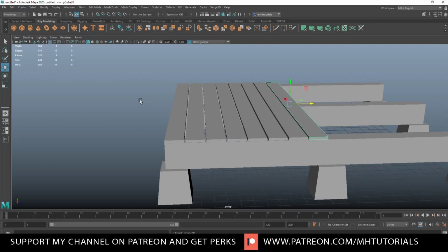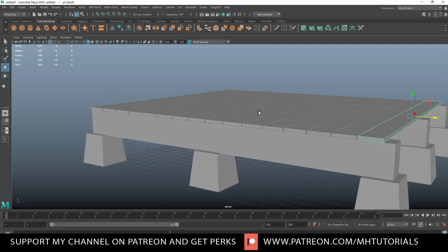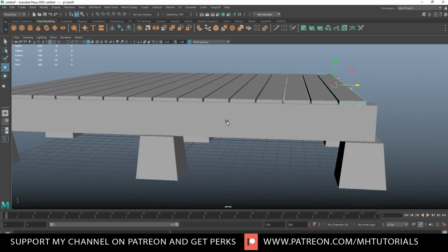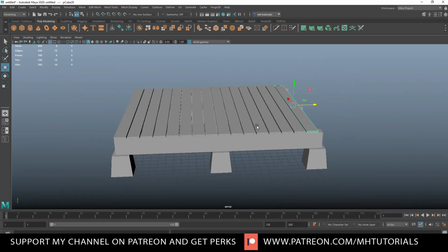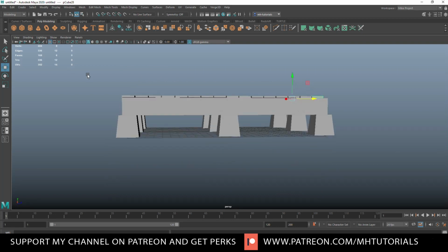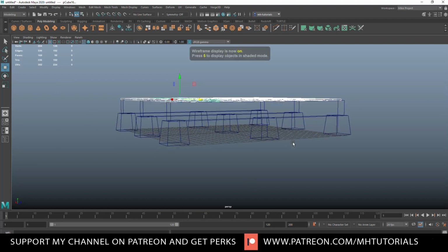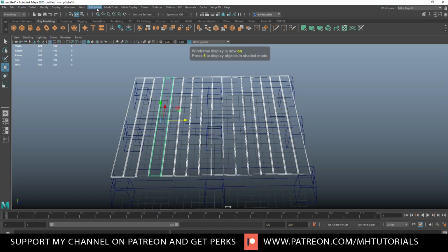And then we're going to hit Shift D and move that over, right? Now, as you can see, we're missing just a little bit of space there. There's an easy fix for that. We're just going to drag select it, and then we're going to deselect this and this, hit 4 so we can see what's going on. We're going to go to Mesh and Combine.